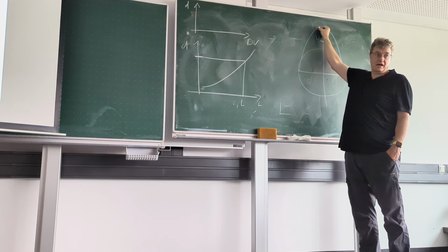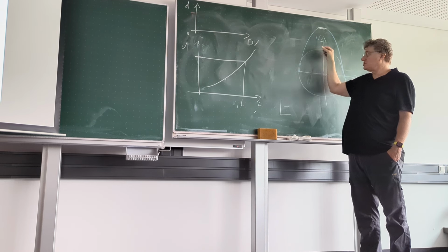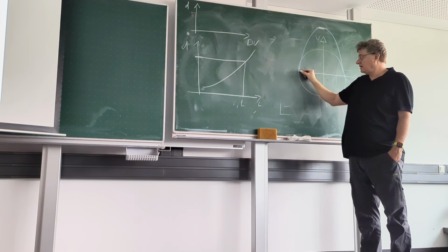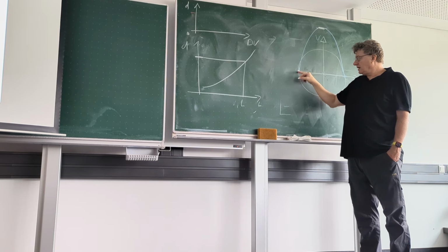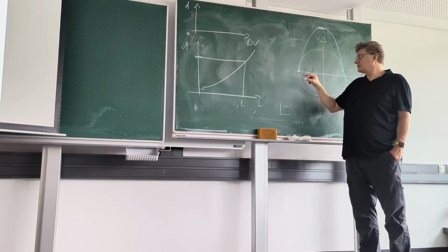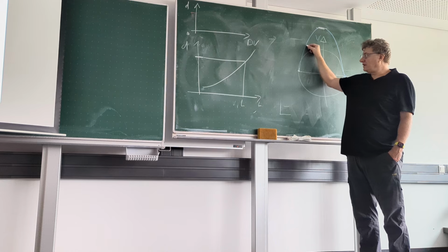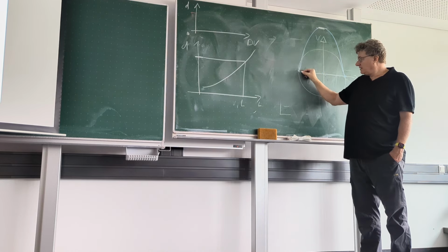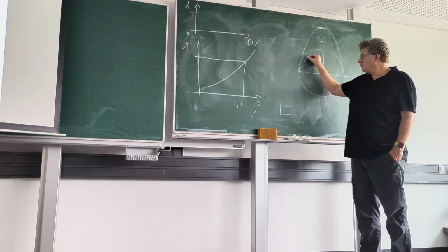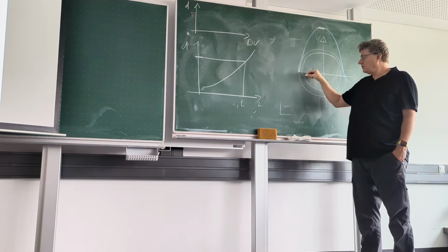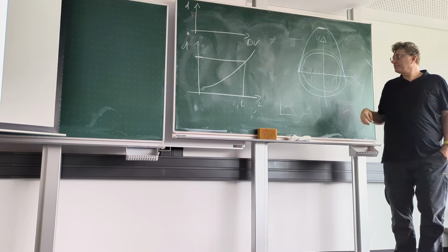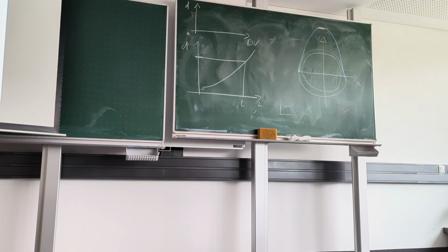So the velocity is high, but it's not changing a lot. Where it's changing a lot is in the boundary, because friction is kept to 0 in most cases, and then it increases kind of quick. So this is a very narrow region in here, which should be resolved very fine.